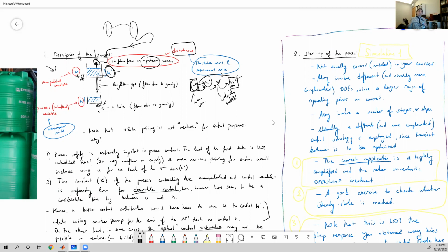So that is one interesting point. You probably think disturbance is a bad thing or something undesirable. Well, the thing is, this disturbance is something which is going to change the H value, the controlled variable, but it is independent of our manipulated variable, or we cannot manipulate it. That is the idea of the disturbance. So for this case, the architecture of the process itself, how it is designed, prevents us from taking any variable as the manipulated variable, as our variable which we can change. Impossible. So there's not much we can do about that. So there's also that constraint.